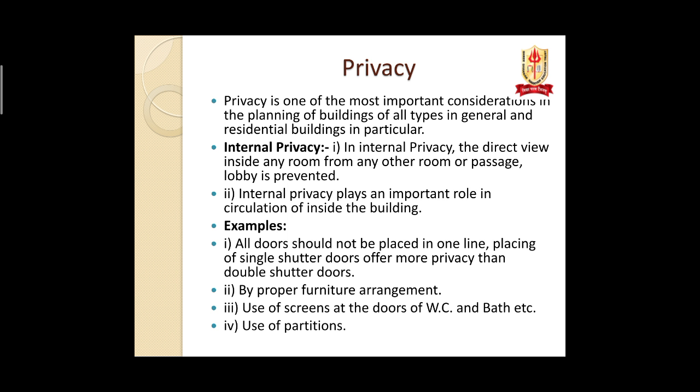Then we go for privacy. Privacy is one of the most important considerations in the planning of buildings of all types in general and residential buildings in particular. There are two types of privacy. First is internal privacy and second is external privacy. In internal privacy, the direct view inside any room from any other room or a passage or lobby is prevented.